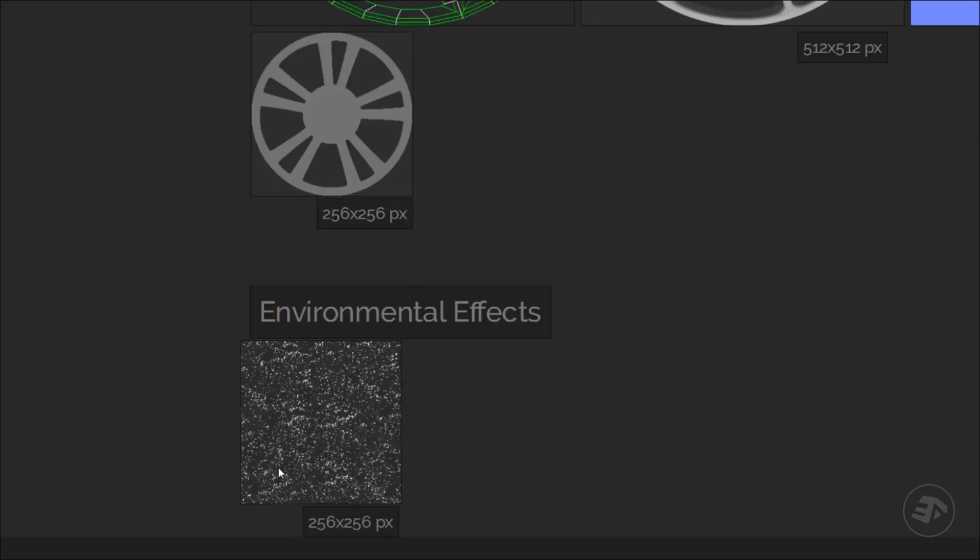However, there are also other maps that you need to take into consideration, such as maps or textures which are commonly used to mimic environmental changes or effects. For instance, this dirt map is one of the environmental effects that will be applied to the rim during play time. You can create a custom dirt map for each vehicle rim. However, most of the time, the game engine utilizes common textures that can be applied over multiple assets. This technique is used to save both time and effort, and also to improve performance.